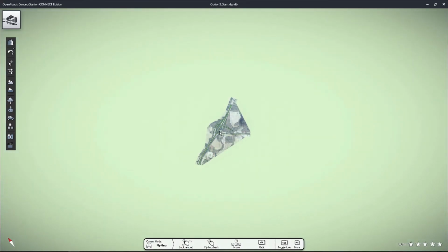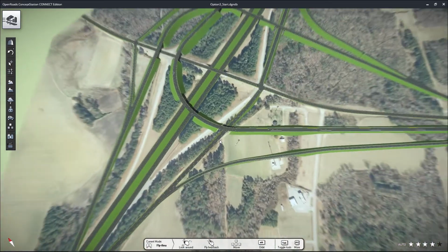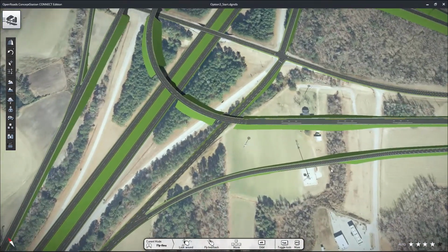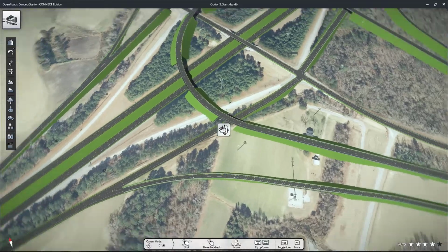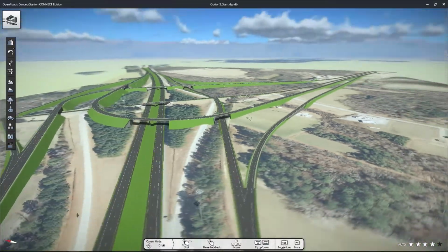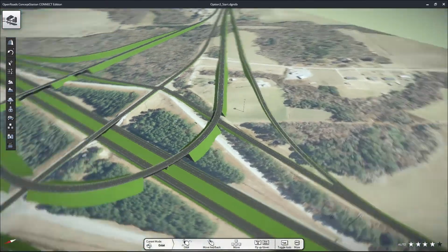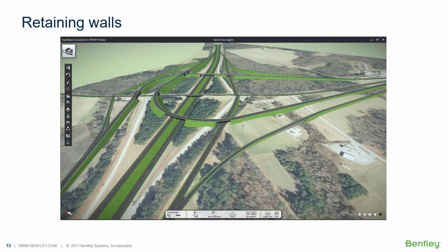So here we're going to go now, the skeleton is all in place, so now we can lay the skin or go to visualization. You can really think about, once you have your design, once you have the bones in place, then you can take it out to LumenRT. LumenRT is part of the product. It's more of a LumenRT Lite, but you can do visualization and create a cube if you want to send it out. So this is just taking it out, and at this point, if we wanted to augment the design with additional trees, vehicles, which we'll be doing in a little bit, you could.